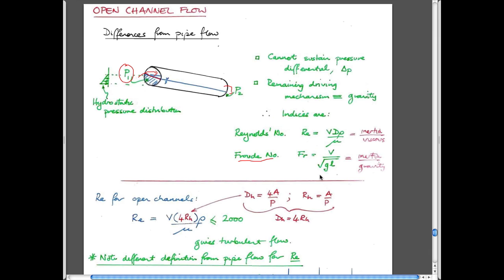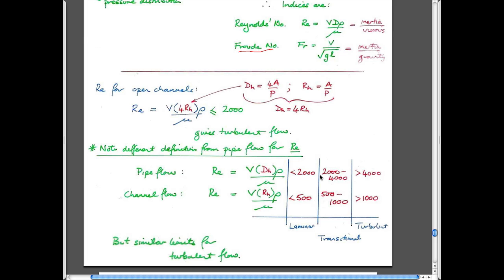We talked in pipe flows that the behavior of the flow regime was a big factor. So we talked about these two regimes, in closed flows and also in external flows. And that is at low Reynolds numbers, then viscous effects are important. And therefore viscous drag and viscous lift are important at low Reynolds numbers, like the Stokes settling problem we did. And at much higher flow rates, the Reynolds number is high and the friction factor remains constant. And most of the drag or lift or the friction that occurs in pipes is due to momentum changes and turbulence, development of turbulence. So we have those two regimes. And those two regimes exist also in pipe flows.